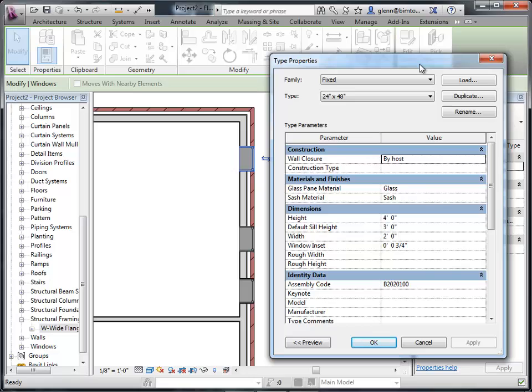On the Y2E2 building, they're all recessed about 5 or 6 inches, so the windows are a little bit back from the wall surface. And if you want to have an accurate model with something like that, you can control that with this window inset parameter. So currently it's set to 3/4 of an inch. If I'd like to go ahead and pull it back to 8 inches or a foot or whatever it is you want to put in there, when we apply that, you'll see that it's going to affect all of the different ones. Because all the ones that have this 24/48, they are all going to share that same parameter. So you've got to always think carefully about whether you want it to affect all or just some.